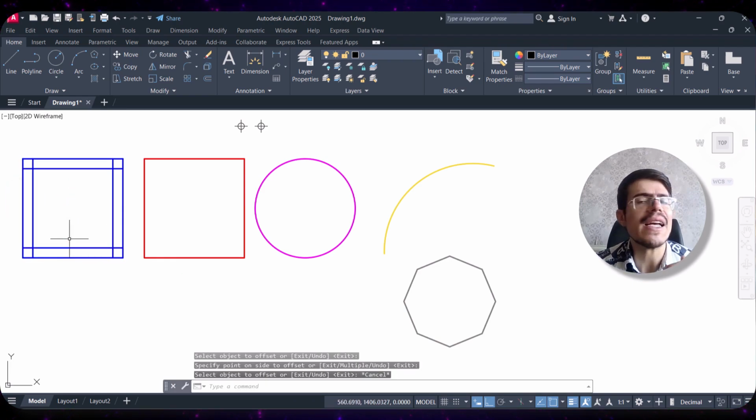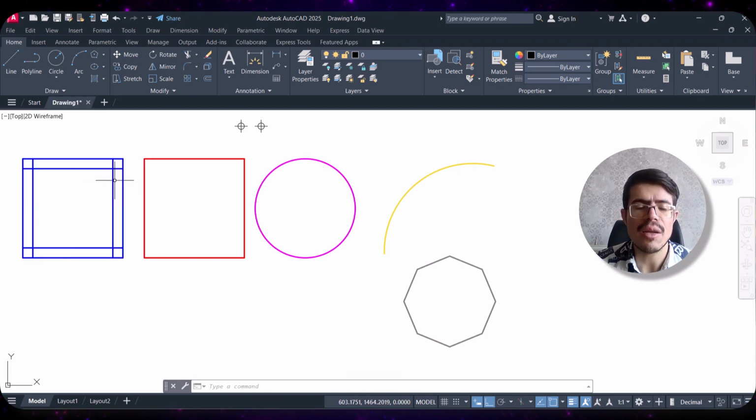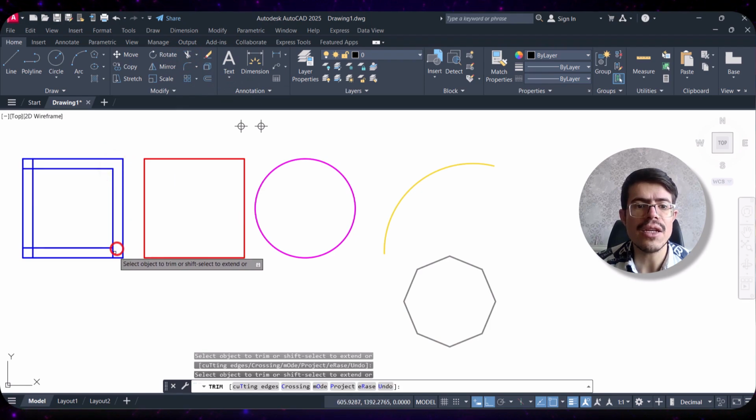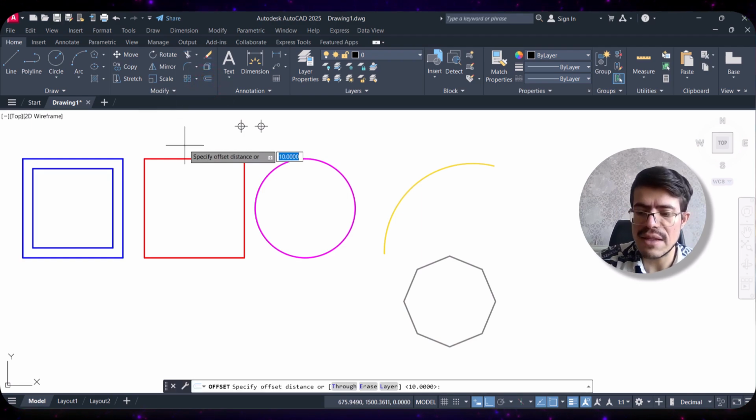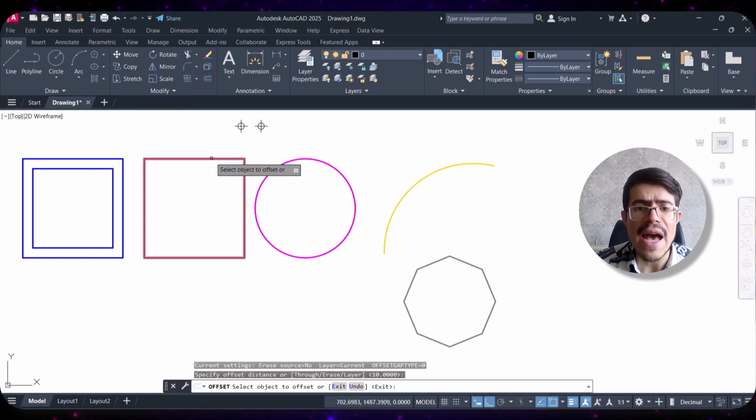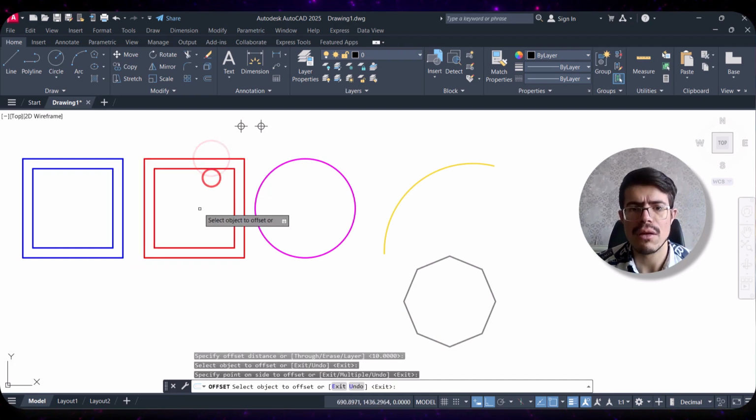As you see, it has been created in the form of lines. So it offset all the parts, and they intersect with each other. After doing this, I would need, for example, to use trim to solve this issue and make them in a clear form of drawing. But actually, you can do it in an easy way. What is the solution? You can again call the offset command, giving the same value, and enter. Now my object here is a polyline. So when I use a polyline, it's done. I don't need to use trim to make my drawing clear.